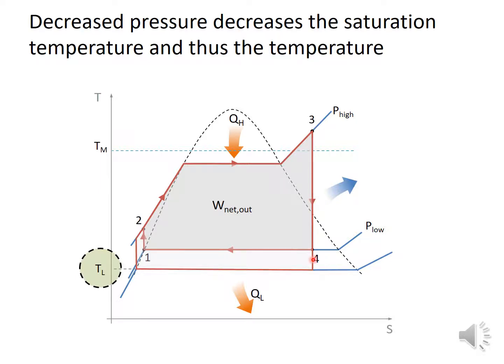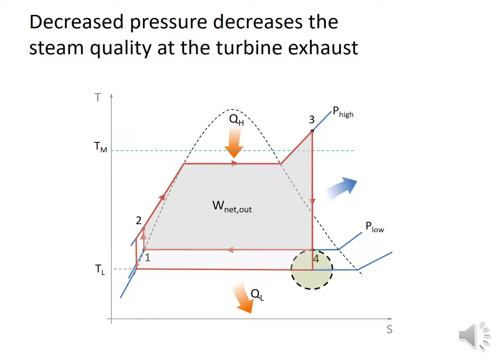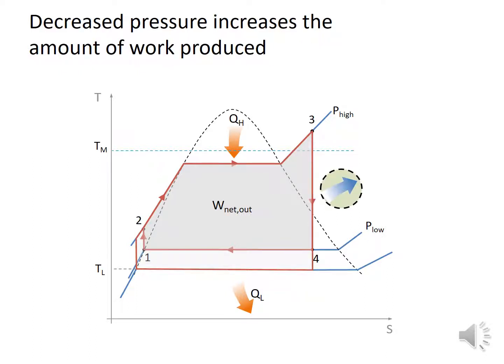And doing that, we see here that we have decreased the pressure of the condensing part, making this type of area a lot bigger. Again, by lowering the pressure, we again increase the moisture content, so we have to be aware of the moisture content when doing these type of calculations to see that this is in reasonable values. The expansion line has increased, showing that we will get much more work out of this turbine by prolonging or elongating this expansion line.